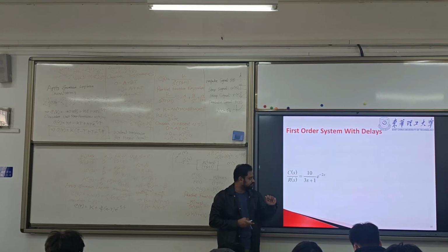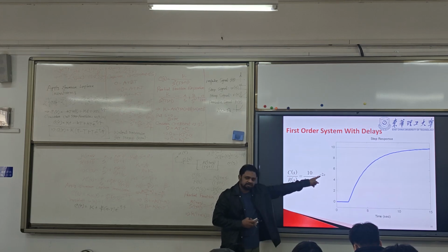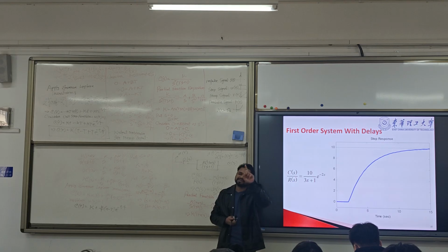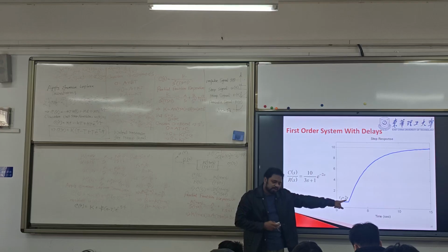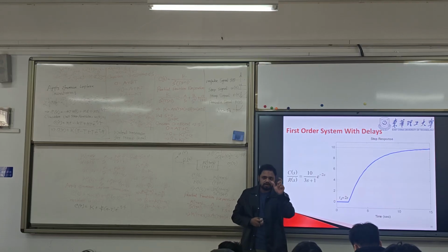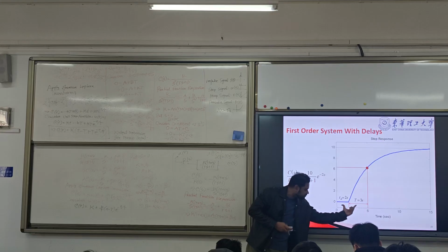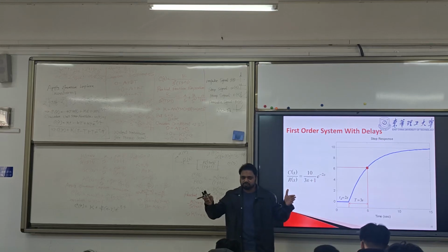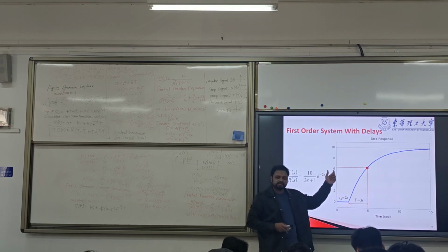Look. Suppose here we have a system. Now we have this TD. And we know the first time constant T, that is T equal to 3, and TD is 2. The system started from here. And now the time to reach the first time constant is 63%, which will give you T equal to 3. Now here, look at this, the time differences. Total time is 5 seconds. Before it was 3.